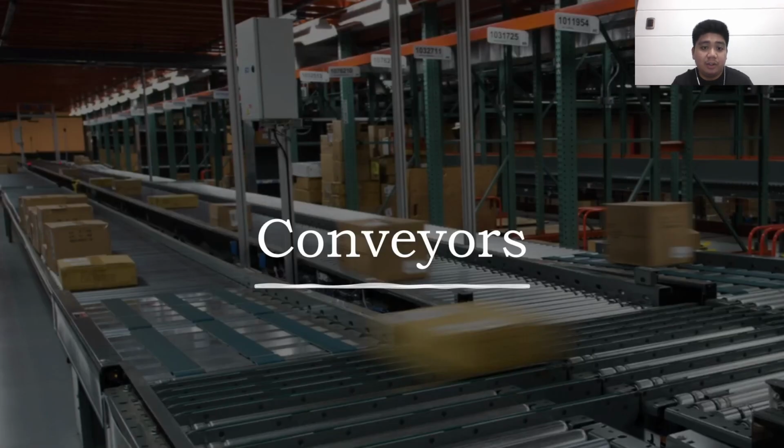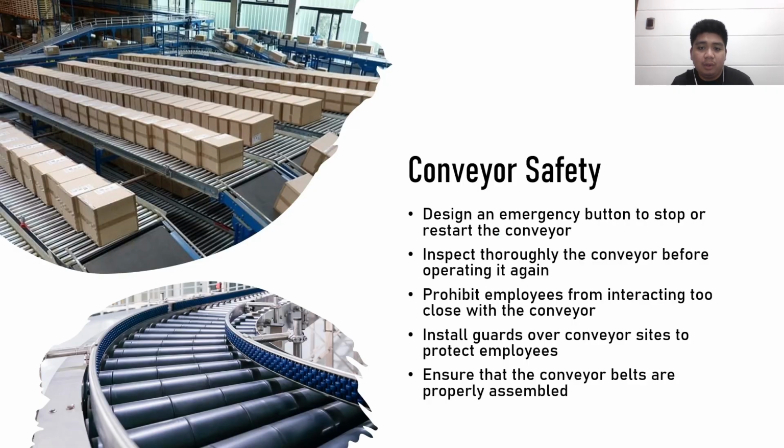Then we have the conveyor systems. When using conveyors, workers may get their hands caught in the nip points where the conveyor medium runs near the frame or over support members or rollers. Workers also may be struck by material falling off the conveyor, or they may be caught in the conveyor and drawn into the conveyor path as a result. To prevent or reduce the severity of an injury, employers must take the following precautions to protect workers.